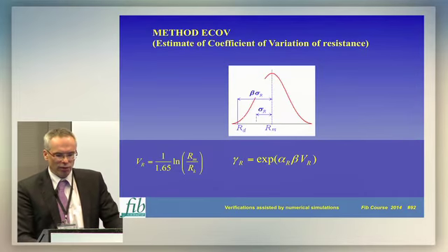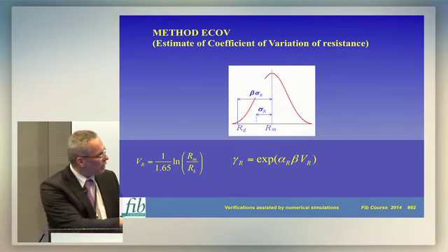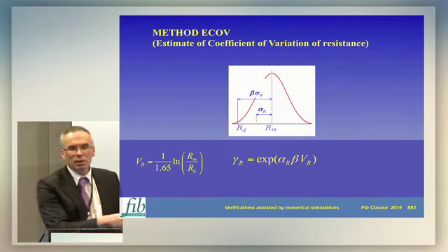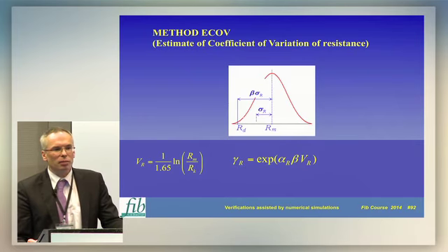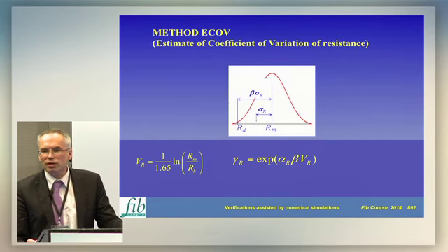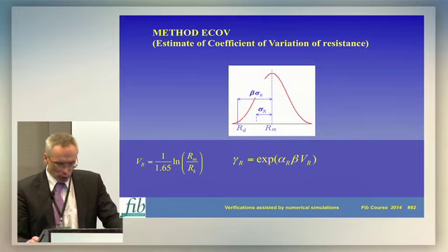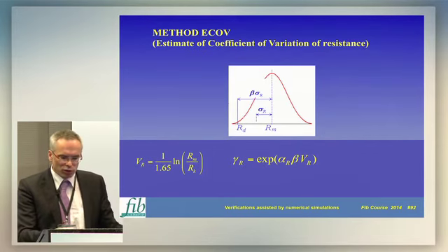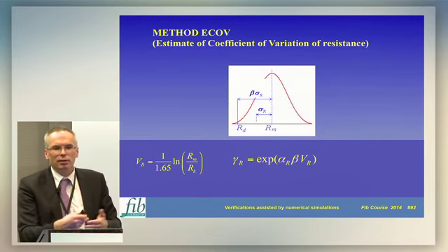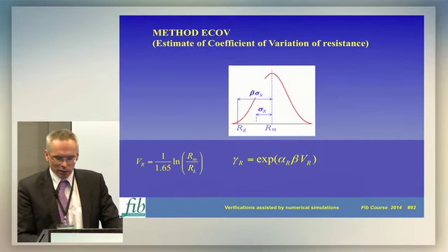Then based on that, it is possible to calculate the global safety factor, considering the beta reliability index, which has been mentioned many times during this conference and also during this workshop. So it allows us to consider the probabilistic aspects or give some probabilistic input data.